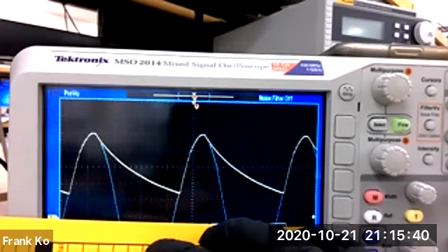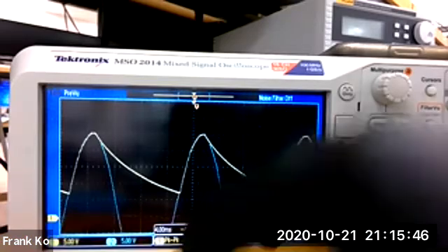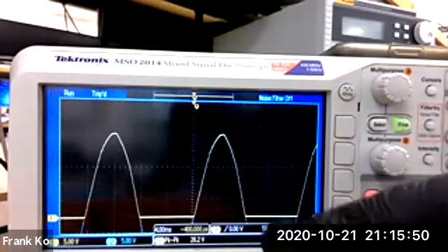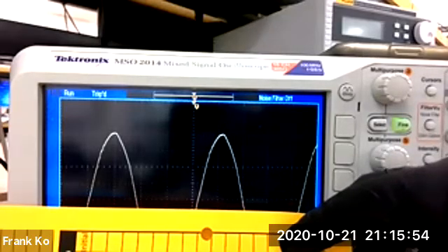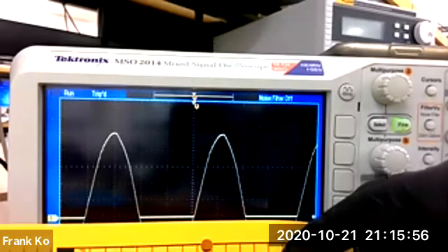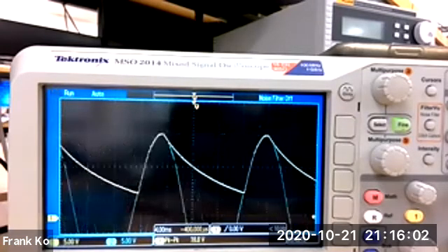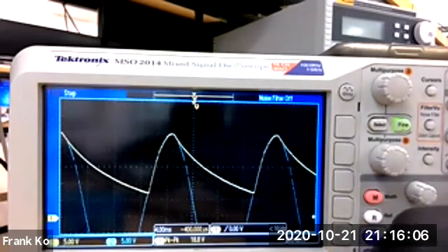Yes. Is the pulsating DC following the shape of the input waveform? Here, watch what happens if I pull the cap. If I pull the cap, put this back on run. If I pull the cap, does the output waveform follow the input waveform on the positive half cycle? Yes? Now, the moment I put the cap back in, watch what happens. Now, the cap was put back in, it stopped so it doesn't move.